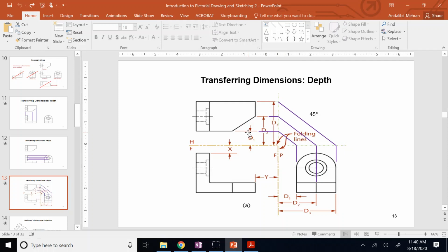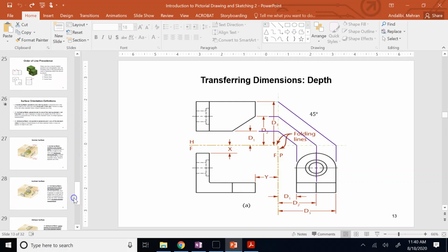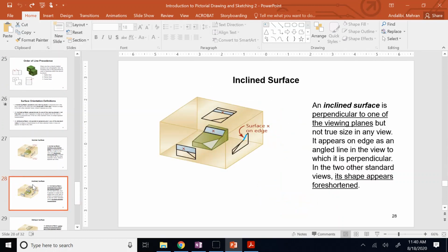here you might wonder about that inclined plane, remember this inclined plane, we talked about it, this guy? Which one of these two rectangles here in the right view corresponds to this plane, this surface, right? Because this surface is a kind of surface that has an angle with respect to the front and right. We call it a type 2 plane. Let me show you. We call it an inclined plane here, like this blue one, but it's not like that. It is tilted with respect to the right plane.